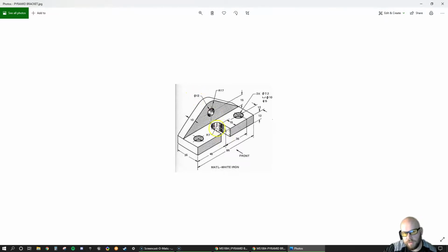This one up here gives you your adjustment. That's why it would be a slot. And then this one here is probably very accurate to whatever assembles to the backside. These holes, I wouldn't want to base these other things off the holes. That's why you see it based off the center, because I can see just by this dimension that these are